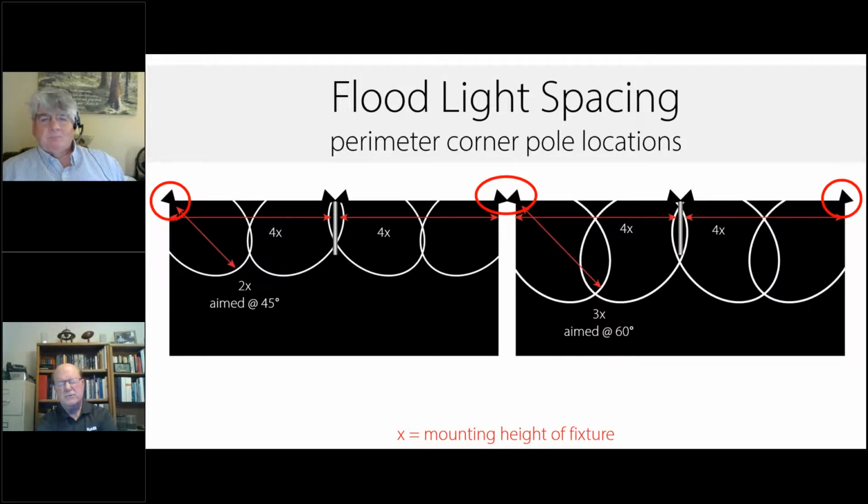Okay. So just for your general applications where maybe you're putting up 2, 3, 4, 6 floodlights and so forth, some of the things that we just talked about. You may want to use the corner locations if you're concerned about darkness in a corner, and that works for that application. You may want to consider 2 floodlights per pole if you want to improve your uniformity and evenness. Then typically aim the floodlights around 45 degrees, but if you need to stretch it a little bit, you can, but you're going to give up some glare. So that's some pretty good things to remember for just general parking.